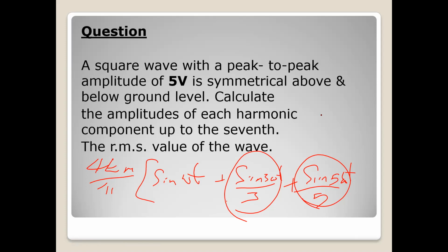I just want to ensure that people understand what they need to be doing. You would divide the value that you get for the fundamental by root 2. You do it for all of them, for 1, 3, 5, and 7, and then you find the sum of all of them.